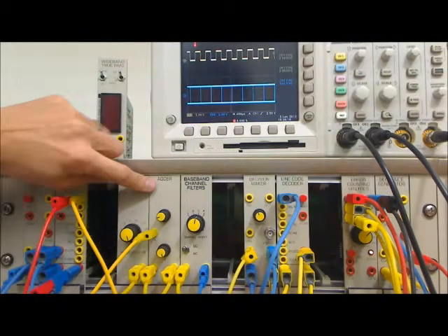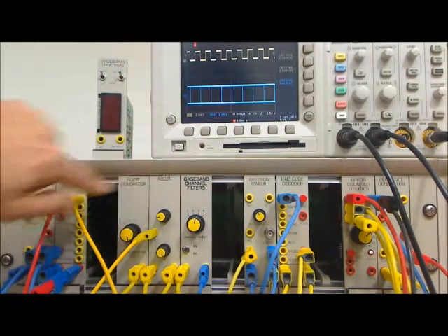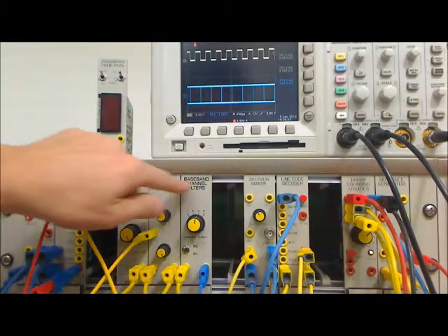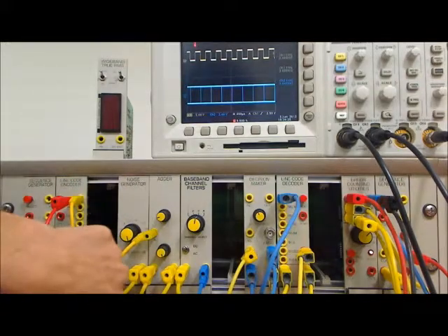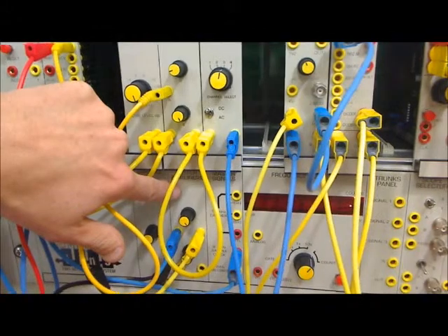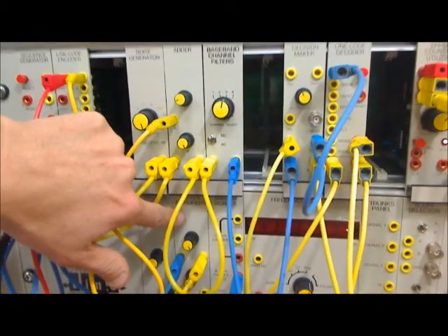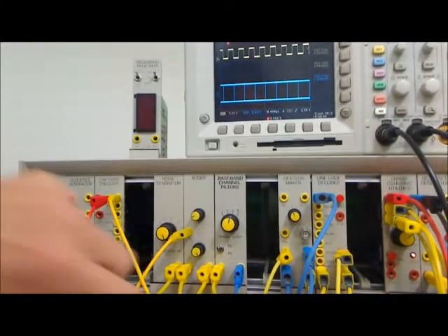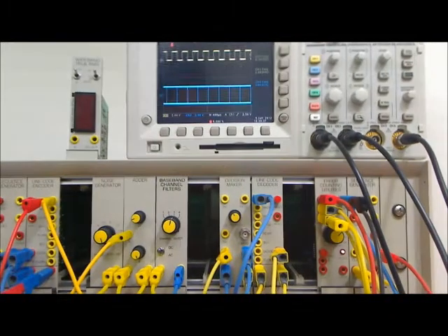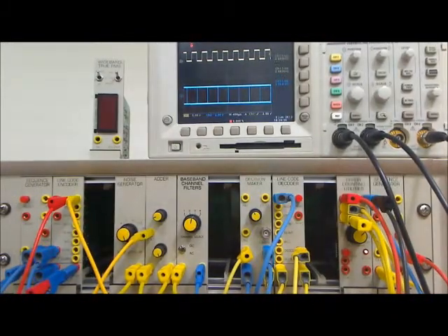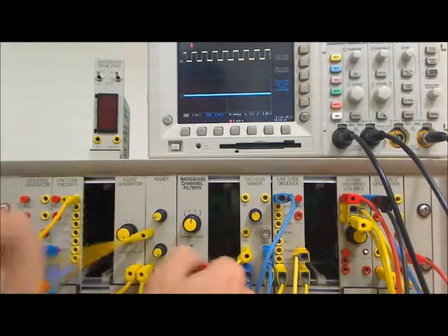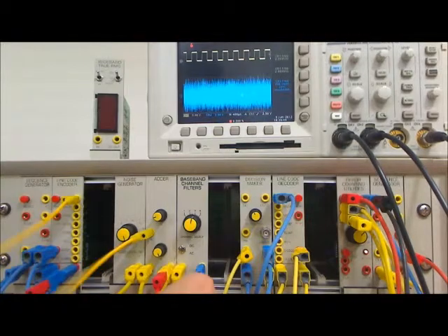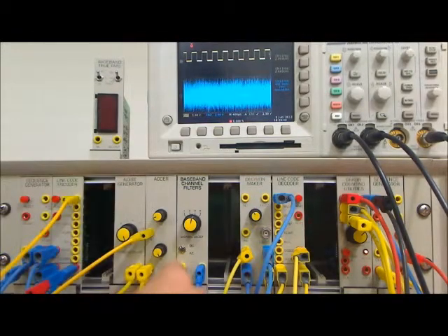and we'll simply introduce another inversion of the signal by passing the signal through the buffer amplifiers, which are down on the master signals panel in the fixed modules. Using the buffer amplifiers, we re-invert the signal a second time so that the signal coming out of the channel is no longer inverted. Let's look at the output of the adder with our probe.